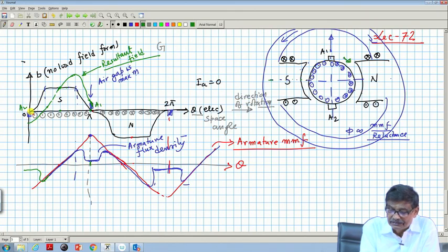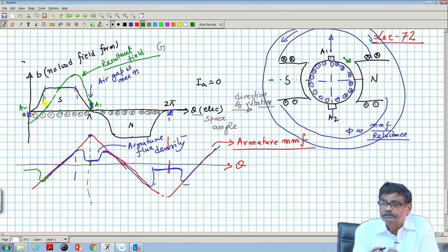This is the leading pole tip, this is the trailing pole tip. So, half of this one is the trailing pole half, and here you see B's are high, the lines of force will be concentrated, and here B value is less, means lines of force will be rarefied over the same area, lines of force present will be less and here it will be more.